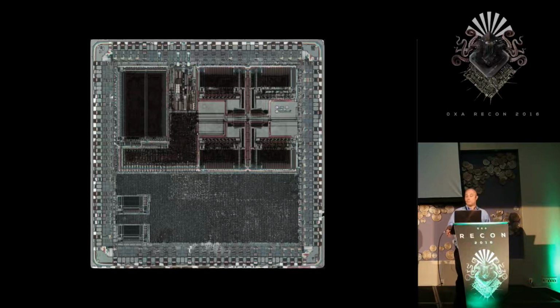Some areas of ROM are now showing visible bits, though, but the other areas haven't been etched deeply enough. So I continue to etch further to try and get a clean ROM. So now we can see the ROM bits. They're quite clearly visible now.